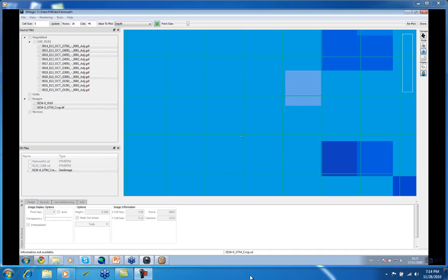So that's the Cube's one way of doing it, that it will have this capture radius which will go around the outside of this cell, and the further away from there, but it's not just a distance, it's also the vertical uncertainty of the point and horizontal uncertainty of the sounding, because it will prioritize the ones with a lower error than the ones with a higher error.